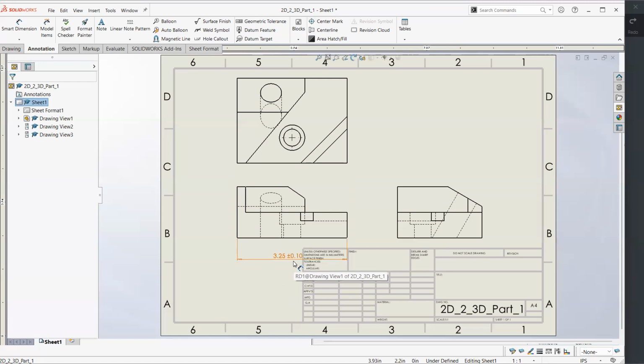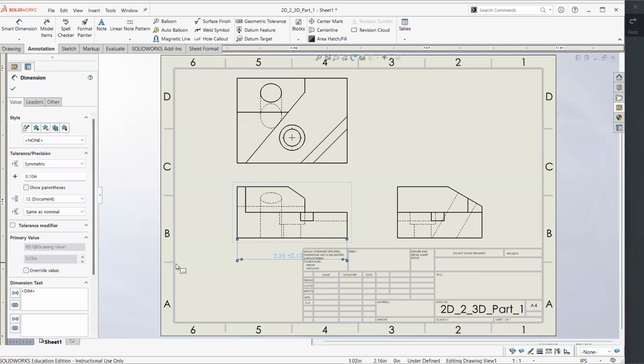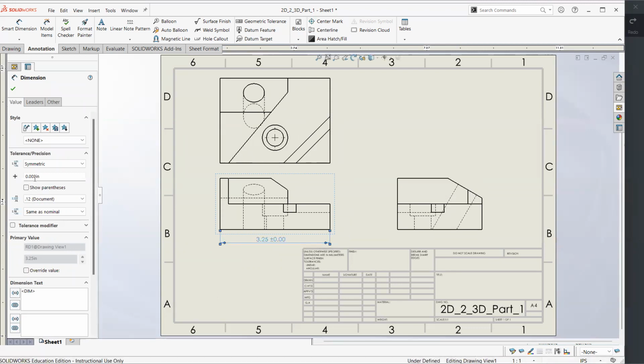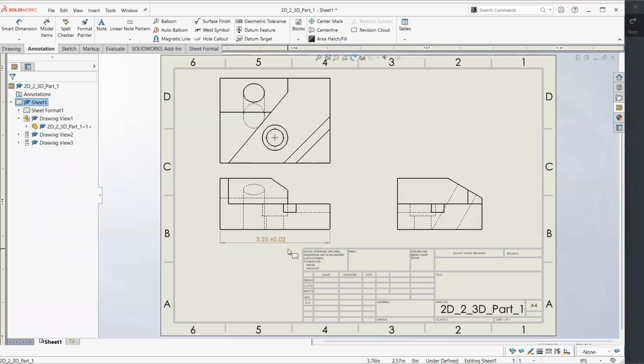And this is what you should aim for if, for example, you would like to put tolerances, since it will make the part cheaper to create. But a lot of manufacturing technologies and manufacturing processes could have very high accuracies. For example, you could have plus minus 0.02. It is possible, but what this will do is make it a lot harder to manufacture this part, since the tolerance or the range for the dimension is too low.